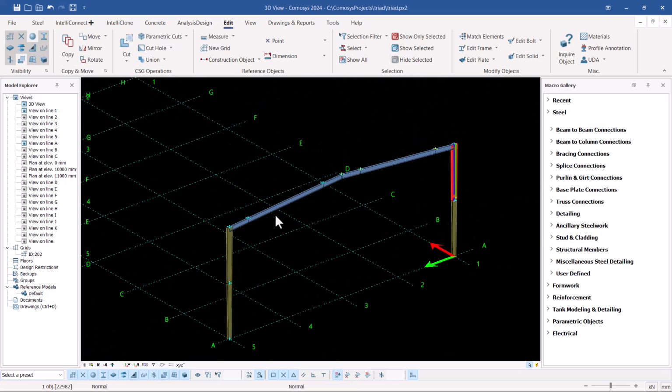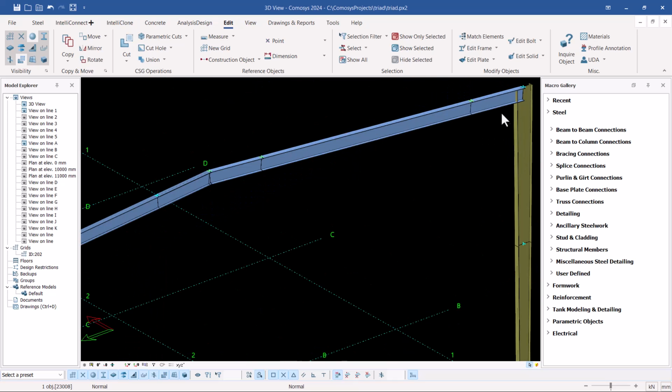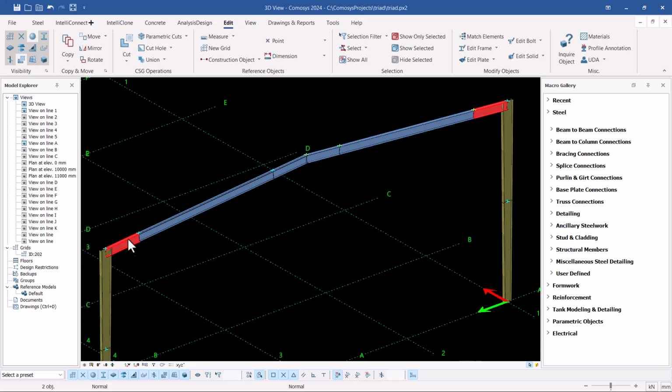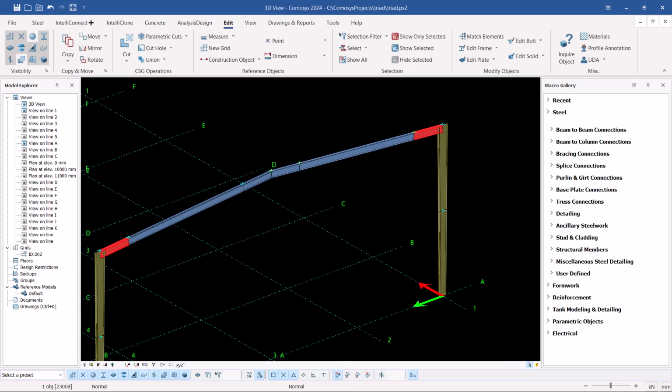So let's go to the rafters. So the rafters, since the size is the same, I'm going to taper this. So this will start from this particular end going this way. So this end will be bigger than this end. So what I'm going to do, I'm going to select that and come here and select that. And remember, our selection will begin from that spot, and come here and double click on this. This will bring in the dialog box.